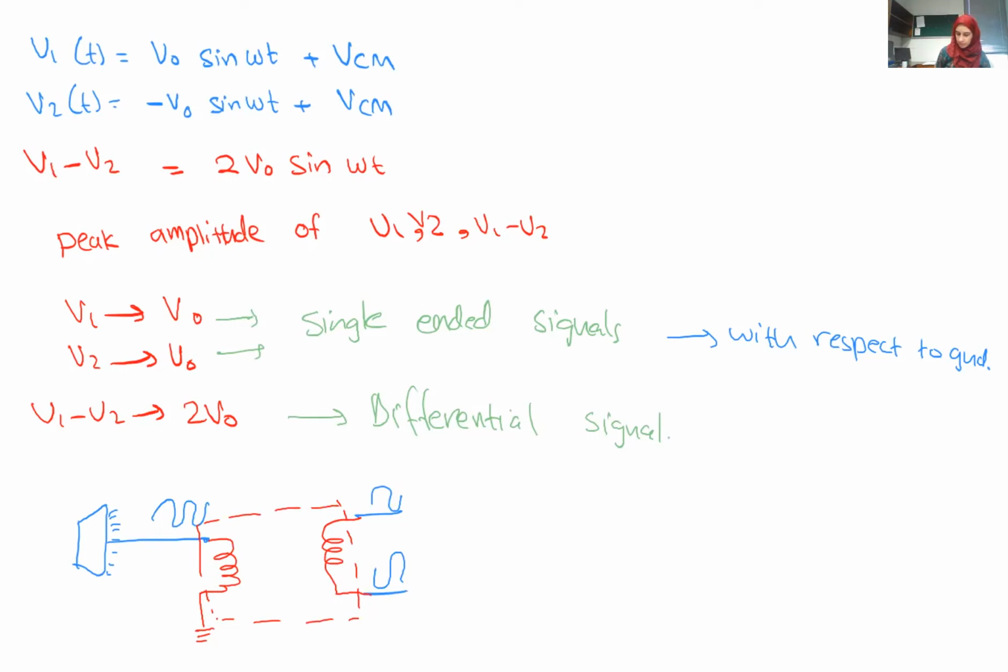I mean, there are multiple other ways. Okay, now if there is any noise that comes in on this side of the signal, then all your output is going to be corrupted. While if it comes on the differential part, it's going to be canceled, because your signal is ultimately the difference between those two signals.